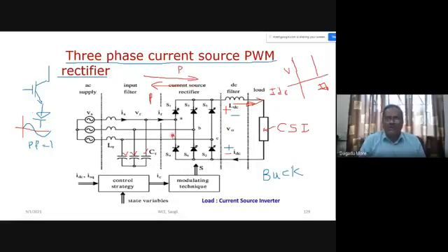And the GTO, like a thyristor, has forward voltage blocking and reverse voltage blocking ratings that are the same. Similarly, for a GTO the forward and reverse voltage blocking ratings are the same. So a single IGBT can be used here, but if you want to use an IGBT or MOSFET, we have to put a diode in series with it.